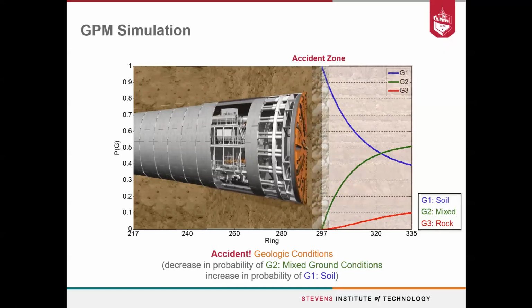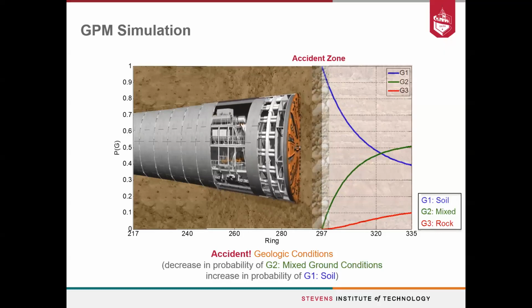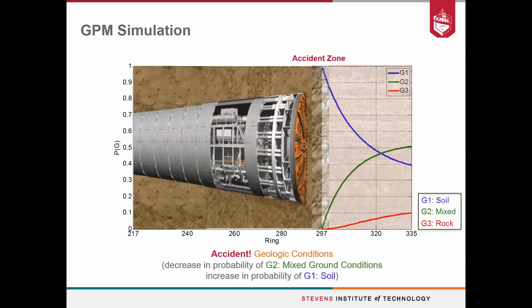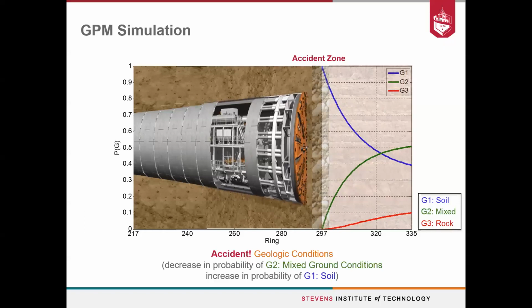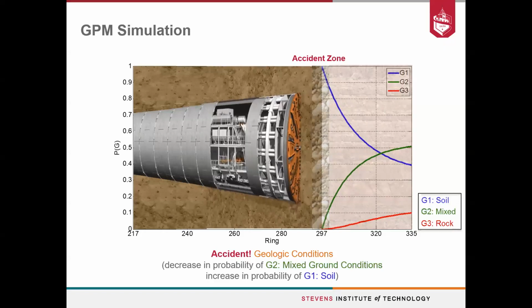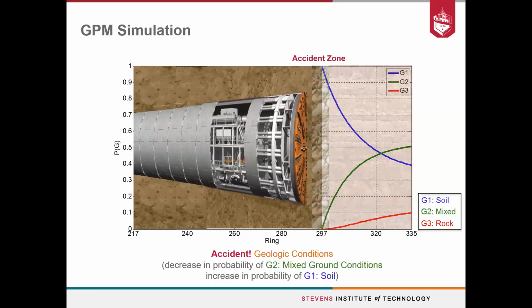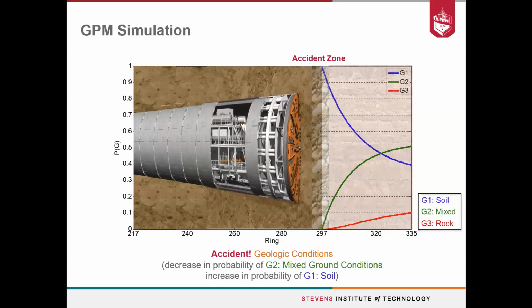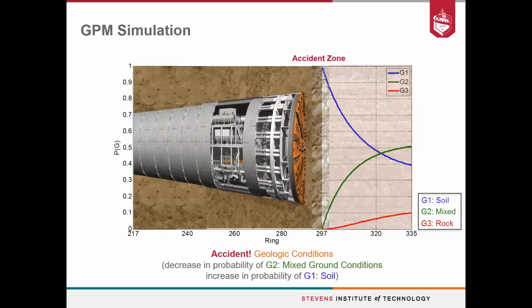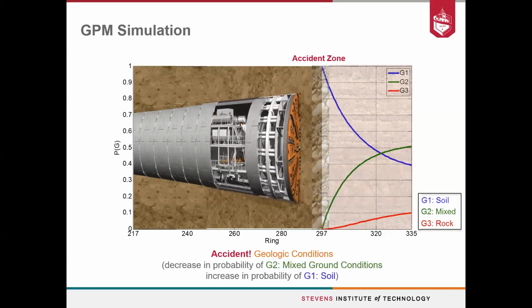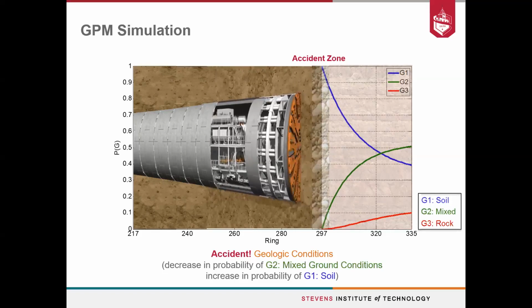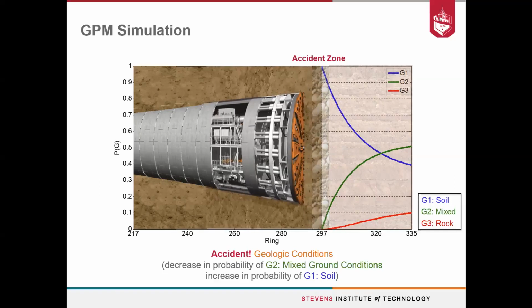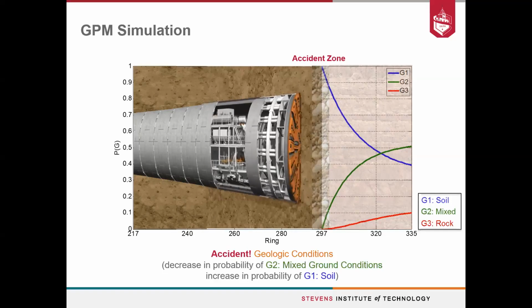Yeah, so you do have some TBMs that have geophysical measurements. One of the issues is for some particular techniques, you have to stop the TBM. You cannot use it in advance. Another one is that they are not a direct mapping. It's not that you can actually see exactly what's ahead of you. You have to go through a process of interpretation as well.